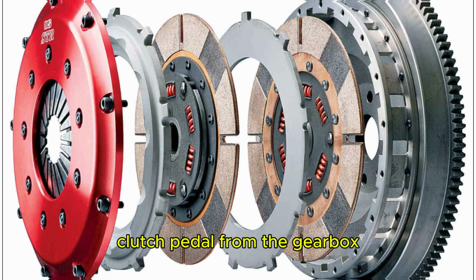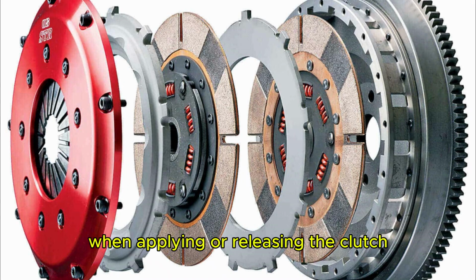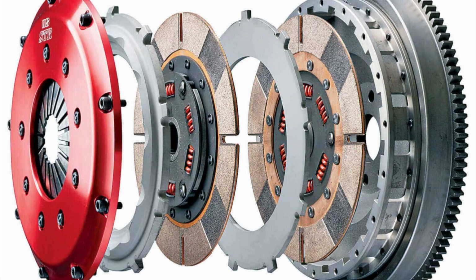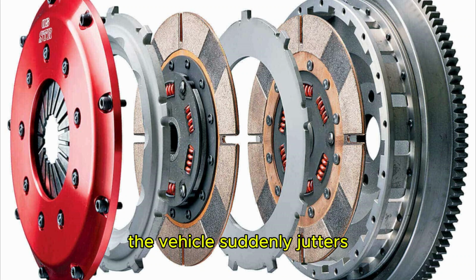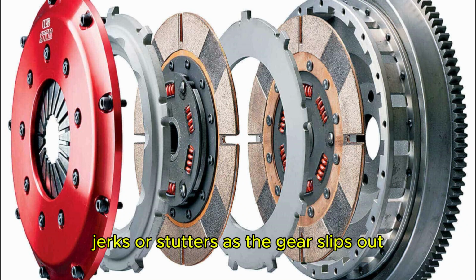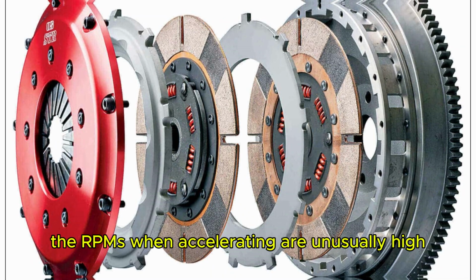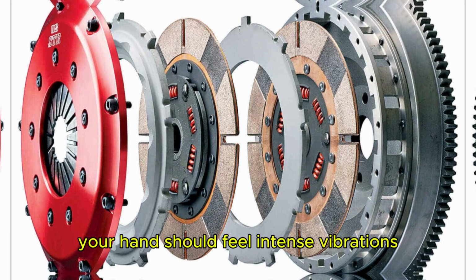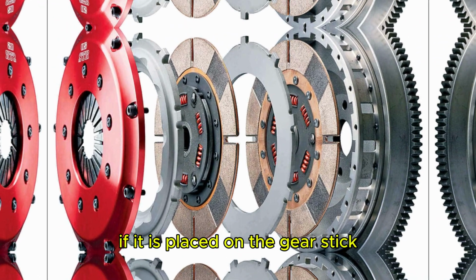From the gearbox, grinding sounds are coming. Difficulty changing gears when applying or releasing the clutch. When traveling forward or changing gear, the vehicle suddenly judders, jerks, or stutters. As the gear slips out, the RPMs when accelerating are unusually high. Your hand should feel intense vibrations emanating from the gearbox if it is placed on the gear stick.